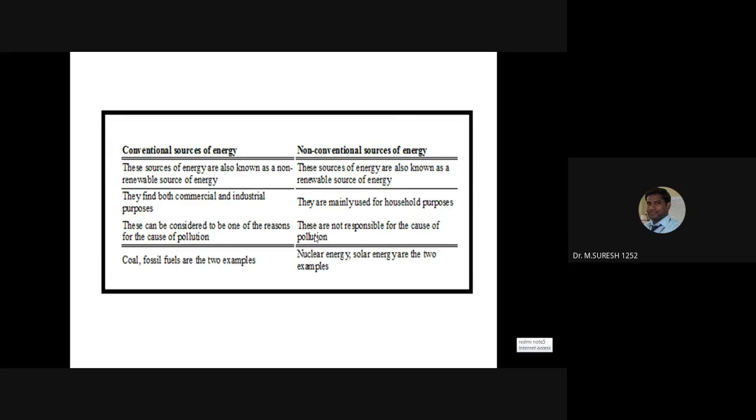When controlling NOx, or oxides of nitrogen, we have to use a catalytic converter. Also, how do we control NOx using cerium oxide? When we use biodiesel or any biomass energy conversion process, a small amount of cerium oxide can be added. That cerium oxide can definitely reduce NOx emission. Not only cerium oxide, but the exhaust gas recirculation method can also be used.